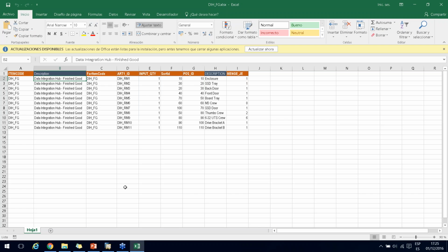In order to enter a bill of material, you will have to create first the items that go to the bill of material, if they are purchased or they are produced or whatever. If you're going to enter an operation or a routing, you will have to first create the resource. So you have to go through previous steps in order to get the whole structure complete.